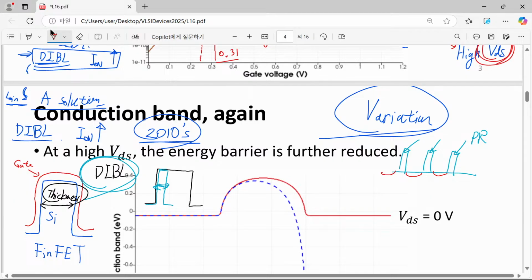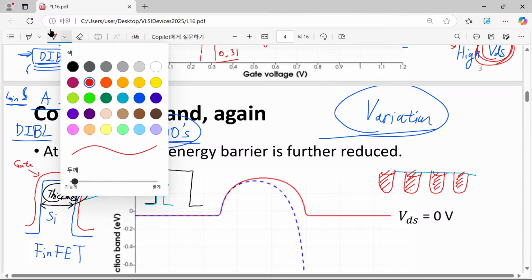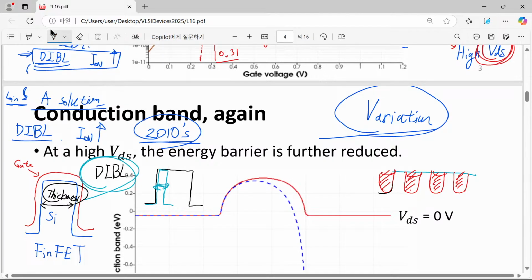If we make a deep etch, then we will have a deeply etched silicon part. So now let's say that the red part, previously silicon, is now gone. After that, this PR is just stripped away. Then what we have is given as this black surface.